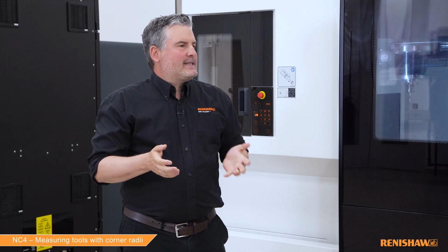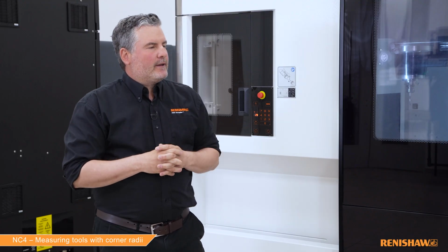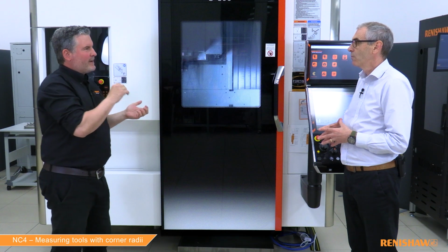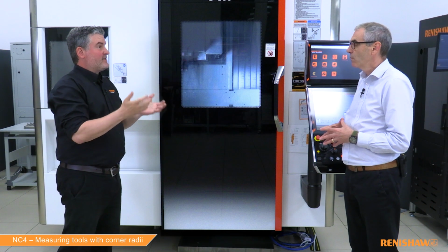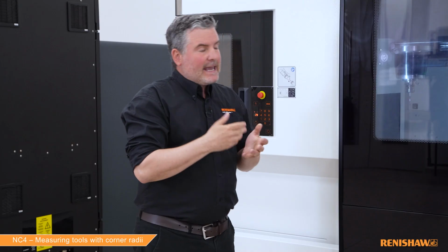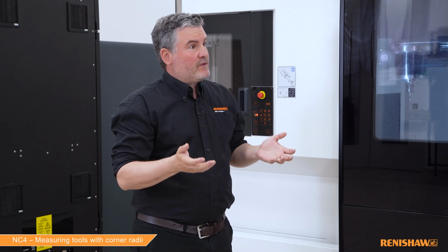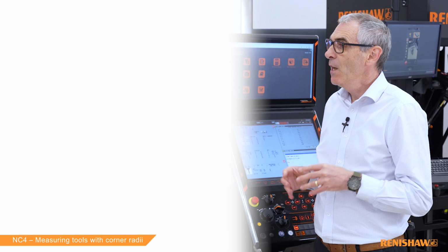So what cycle are we running today and what can it do? Today we're running cycle 9867, which gives us the ability to measure the corner radius of the tool, as well as the tool's length and diameter. As I remember, this cycle is slightly different to our other measurement cycle, which is the 9862 cycle. Here, the B input is related to our tool shape. So B1 is for bore nose cutters, and B2 is for end mills or slot drills, but with a corner radius. Yes, that's correct.